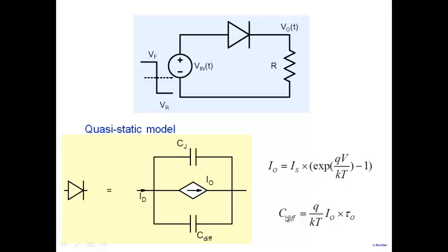And this capacitance, for example, we calculated by assuming a certain profile of the injected hole density, which we get from steady state calculation. So we are assuming that the profile still remains the same, even under transient condition. The injected holes may be changing with time, but the shape still remains the same.